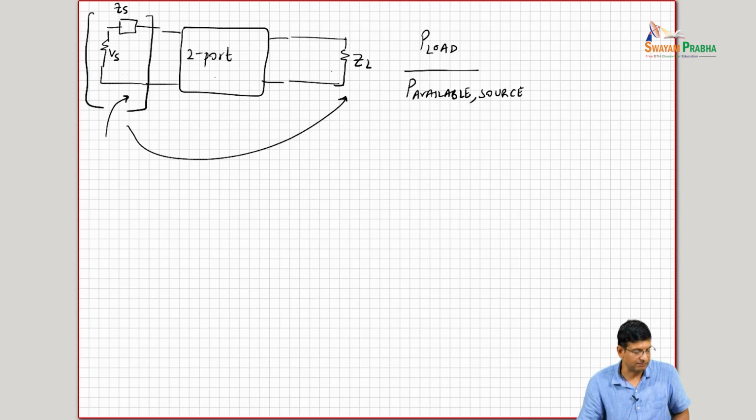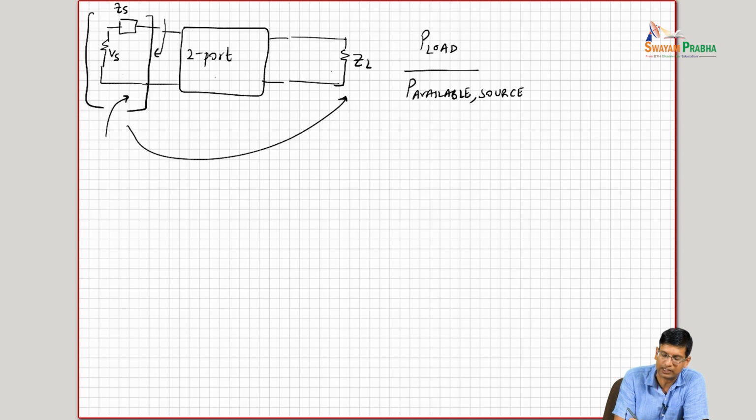Logically, Pozar and Gonzalez have derivations in terms of S parameters for all of this. We'll just take an intuitive view here. Logically, it seems like what should happen is that I should make sure that I extract as much power as possible from the source. So I should conjugate match the port and the source at the input.